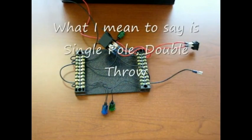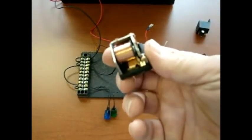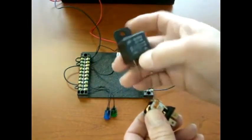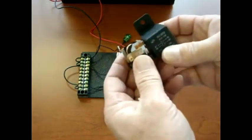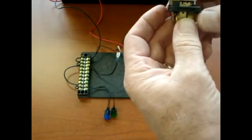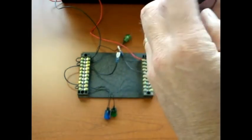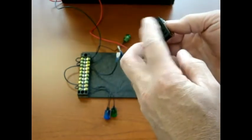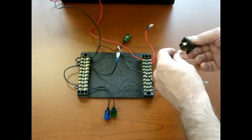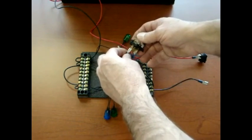Now let's take a look at the double pole, double throw. So here's that double pole, double throw that I showed you before. It comes in a housing just like this one does. We've just removed the housing to show you the inner workings. So here we have our two coil connections. So we're going to connect from our switch to our coil, and then we're going to connect the other side of the coil to our ground side over here.